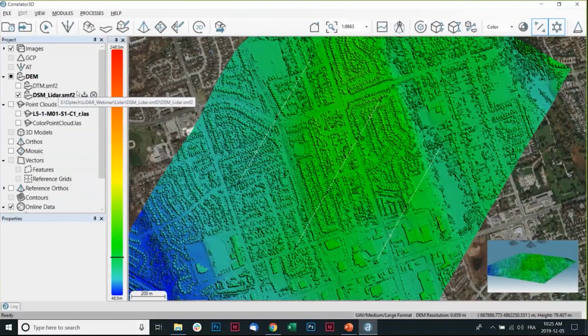So in this case where you're using your LiDAR as ground reference, I think you really want to probably take some ground control points on bare earth data. So you want to make sure that on open area, your photos and your LiDAR are well matching together.